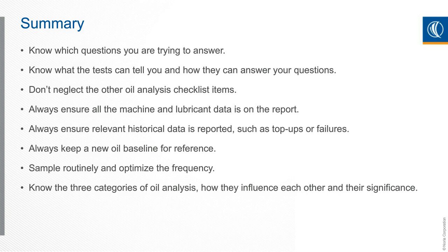But to summarize some of the things we talked about today and how to maximize the value of your oil analysis program, you need to make sure you know what questions you're trying to answer and know what tests can tell you that answer, and to pair that up properly. You don't want to neglect other checklist items. Always ensure your machine and lubricant data are on the report.